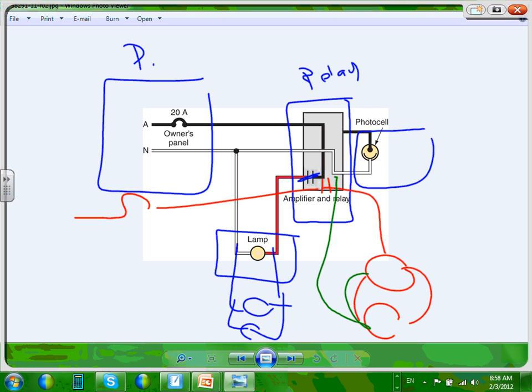So you can put them in 2 different contacts, especially if they're 2 different circuits. You can put them in 3 different contacts. When would you put them in a different contact? If you have two circuits. If you have one circuit, it doesn't make sense to put them in two different contacts. If you have two circuits, you cannot put phase A and phase B tied together in one contact. What's going to happen, Nick? Short circuit. So that's the application.